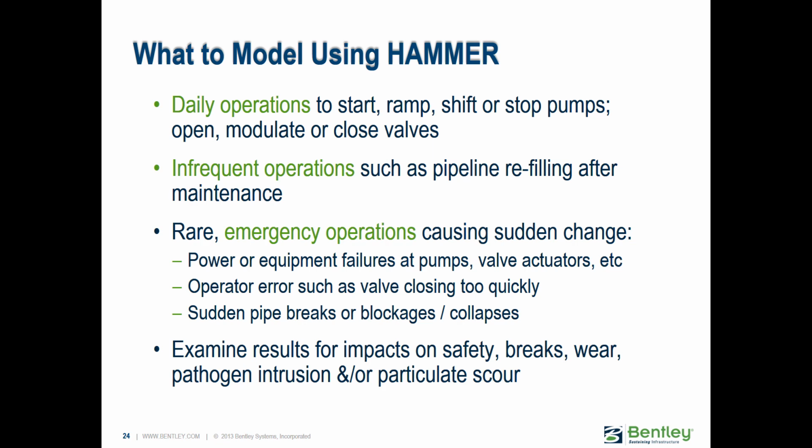That's something to consider. Then if you have negative pressures or sub-vapor pressures, you have to consider what's in the soil around that. Is it going to suck in some contaminants? If the pipes are moving, if you have significant transient forces that will move the pipes, what effects would that have?